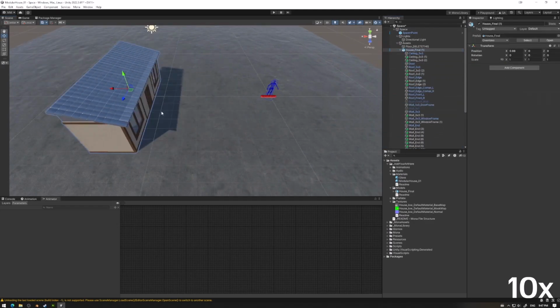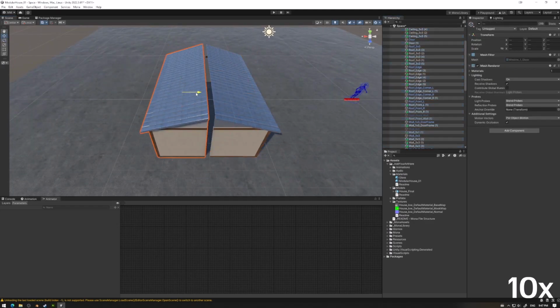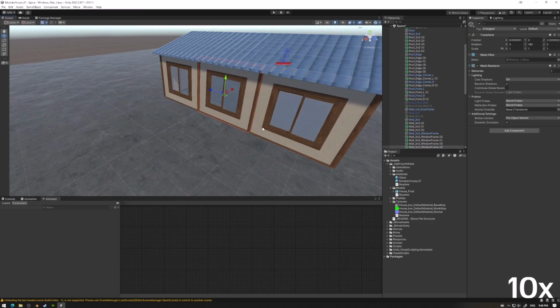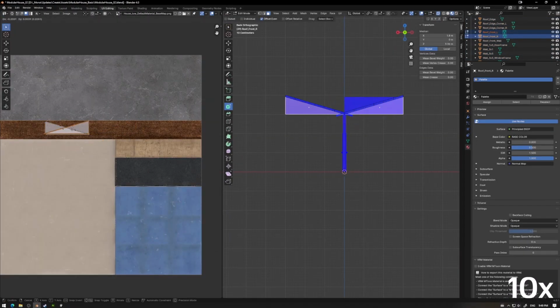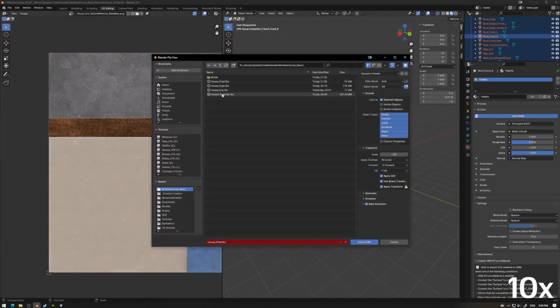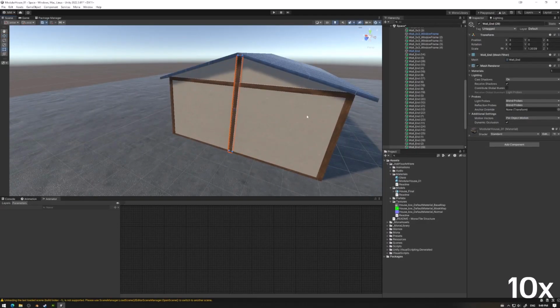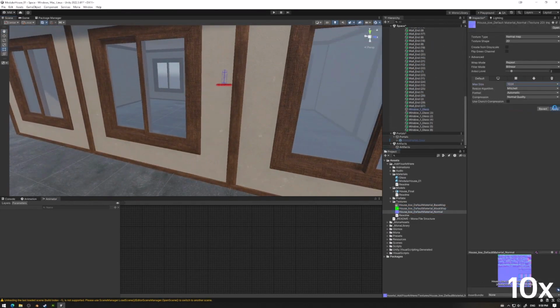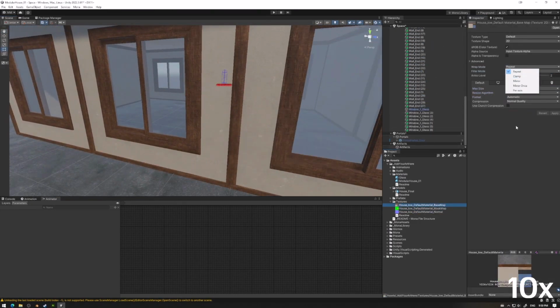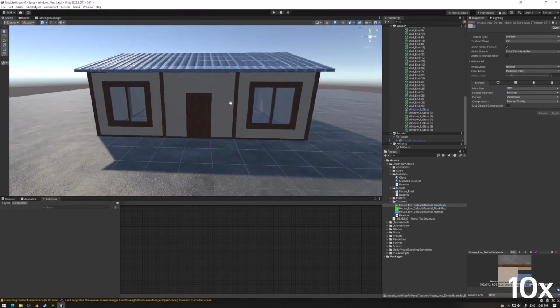Note how the pivot of the asset is very useful in modifying my assets in the space. The pivot is not at the very end of the wall, it is at the base in the center of the pillar. This allows me to easily rotate the wall and continue along without any issue. It is possible to add the pivot to the center of the asset, but as Unity has a center pivot location setting as well as the pivot you set, you can give more options for creating the result.